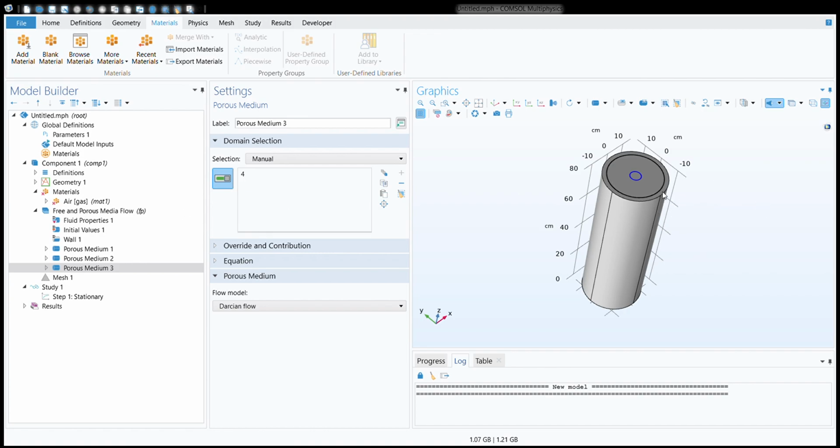Then we have to remove the center pipe, so that we can add a new one. You have completed creating the dome. For that you have to go to difference again. The objects you have to add are this upper and bottom dome. The things you have to subtract are the center pipe. Build all objects. Now we have created a dome with a hole for the center pipe.